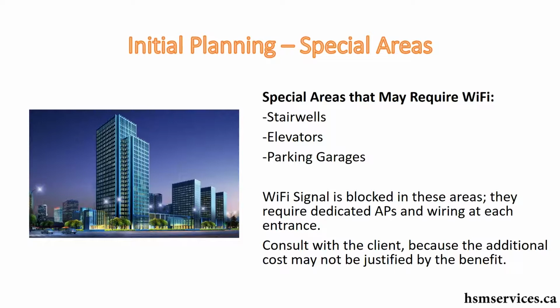So you need to think about also if the client wants to have Wi-Fi in a stairwell and an elevator, in a parking garage. These things are built out of solid concrete, and your Wi-Fi doesn't really get into those areas, so you have to put additional APs, which means additional wiring. Typically, you would put APs at each elevator door or each stairwell door or inside the elevator shaft. And it's very expensive, and you need to think about if the client really needs that and if they want to spend the money.